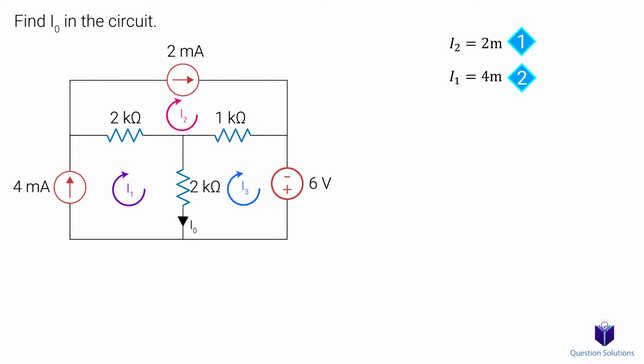Now instead of writing our KVL with voltages, we're directly going to write our KVL with current and resistance instead. If you're not comfortable jumping to this step, that's okay. Simply label the resistors with voltages and write a KVL equation and then come to this step like we did in the previous example. Lastly, we have the right mesh. Let's write a KVL equation with currents and resistances.